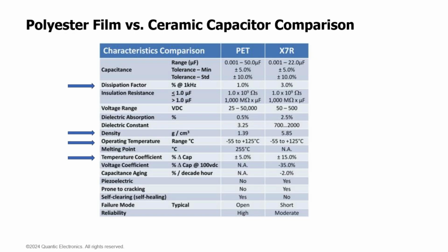So far, I've been talking a lot about the advantages of polymers. Despite these unique advantages, there exist some very favorable properties in ceramics as well, that often make them the primary contender for medium voltage applications in power electronics. The number one advantage, I would say, is, again, the high dielectric constant of some of the most popular dielectric materials. What this allows for is significantly higher capacitance density or smaller overall size. When you're designing anything, especially high reliability devices, size is critical.